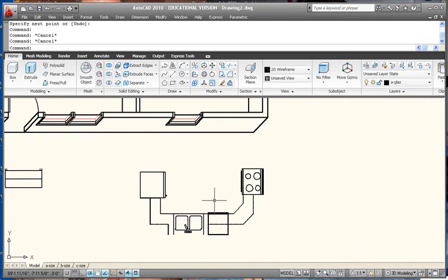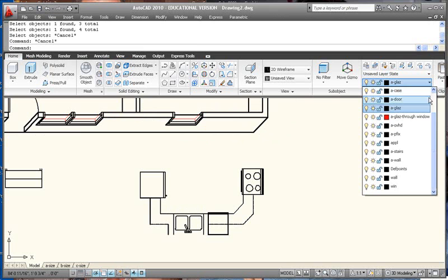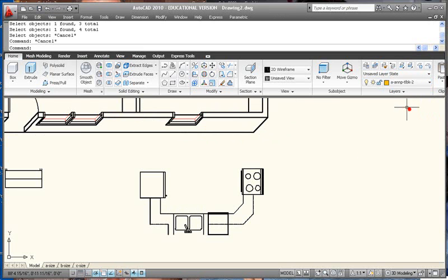countertops. So what I'm going to do is I'm going to take these edges, the front face of the countertops, and I'm going to put them in the correct location based on this edge down here. So I'm going to put in here a line temporarily as a construction line. Let's just use that title block line for now. I'm going to put in where we would see the lower corner of the wall if we were on the inside. That's kind of being hidden by the exterior wall right now, which is why we can't see it.